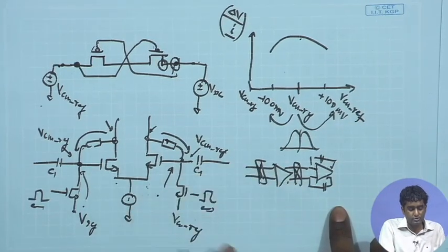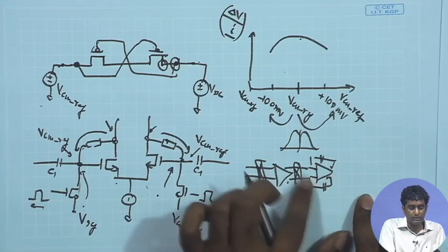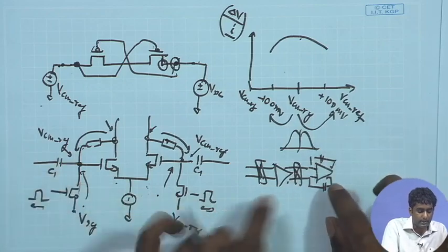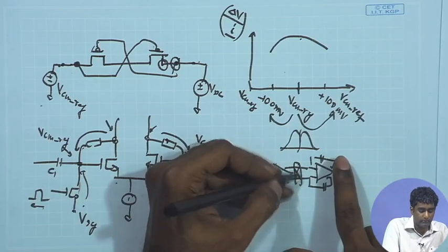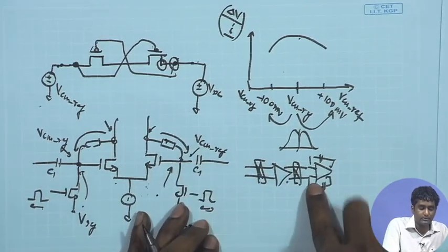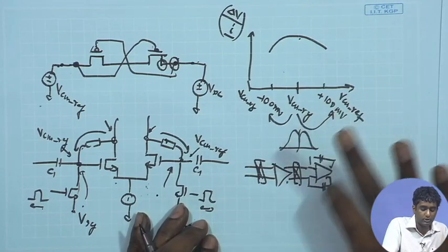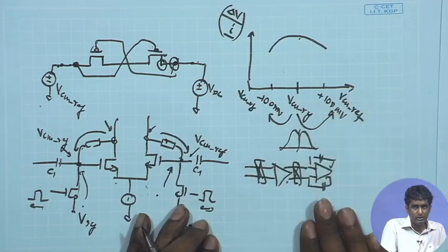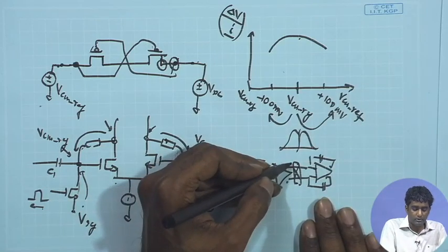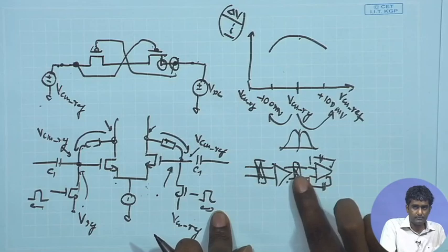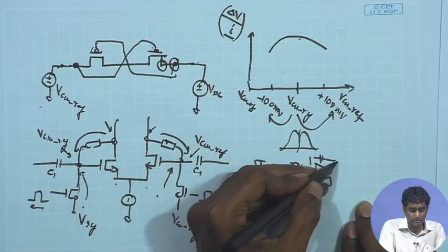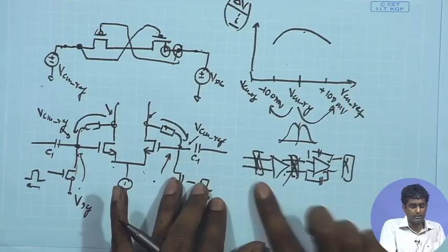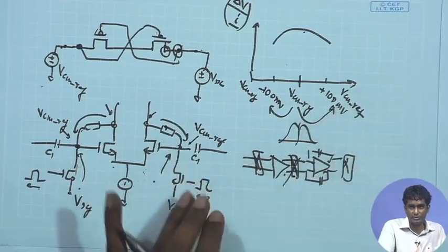So for the second stage amplifier, once again you will need to apply that kind of feedback to settle the input potential at the same point. Under that condition, since you have anti-chopped the signal and the signal is at low frequency, and you are not applying any chopping over here, once again you may need to take care of the feedback resistor also. In many cases it may happen that you do not apply the chopper after the first stage, rather you apply the chopper directly after the second stage only. That may also happen. In that case, both the amplifiers are basically processing high frequency signals.